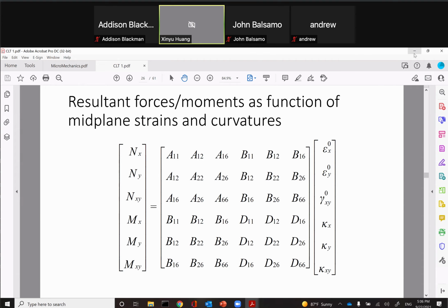So if you're a math genius, you can figure out the rest of it. This is basically the whole series. We're going to do some exercises. You need to solve equations. For the classical laminate code, you need to calculate this matrix. That's the majority of the work. You write a code to calculate all these matrices, given your laminate structure.